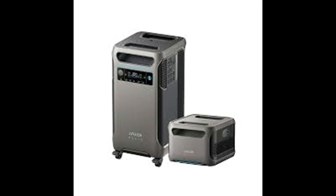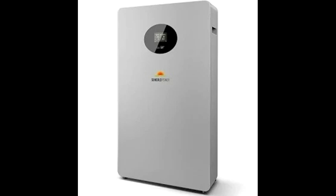Giving the amp hours of a battery pack is only part of the equation. You need to know both the amp hours and the voltage of the battery pack to answer a capacity related question. I think they're just assuming you know the voltage, but you don't. It could be a 12 volt system, 24 volt system, or a 48 volt system, or some other voltage even. So they have to provide both the voltage and the amp hours in order for you to answer a capacity related question.